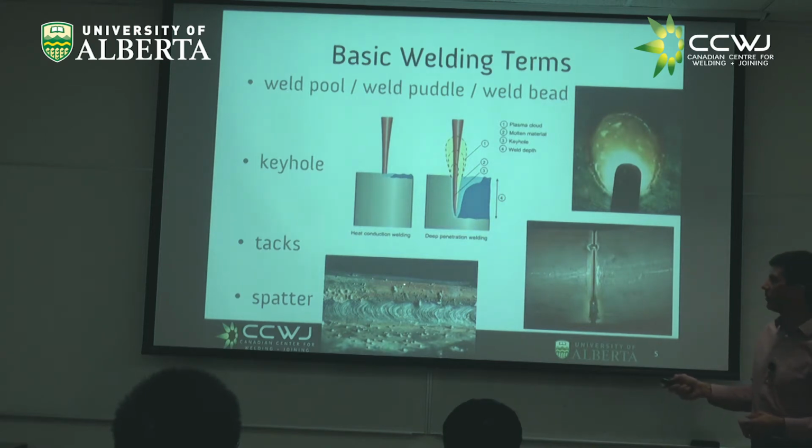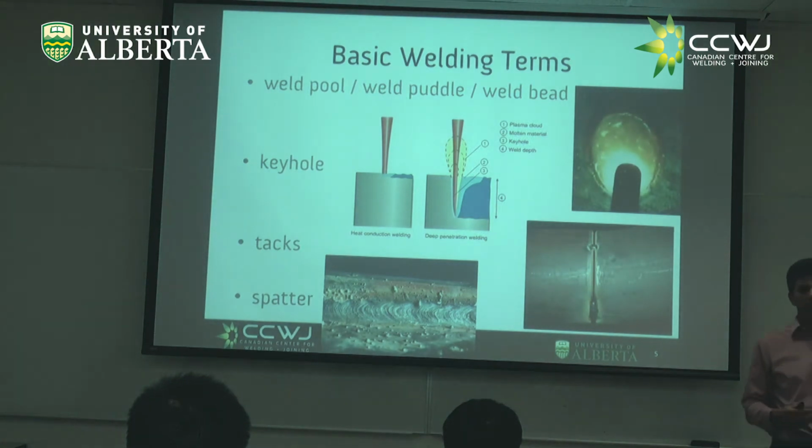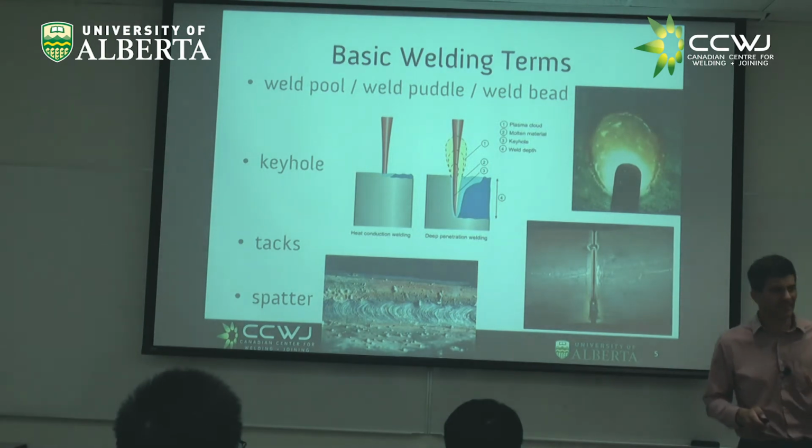The spatter is not good. If you need something that is going to be seen, this is considered a low quality weld. Even if the strength is good, nobody wants a weld full of spatter. Spatter means also steel that you paid for but didn't end up in the weld. It's inefficiency. Spatter also means little bolts of red hot iron that will get through the back of your neck and give you a pretty good burn. So it's not really safe.